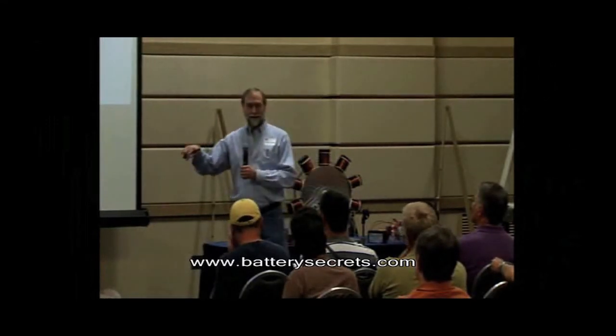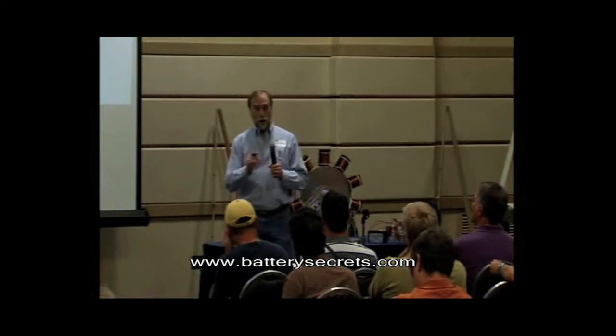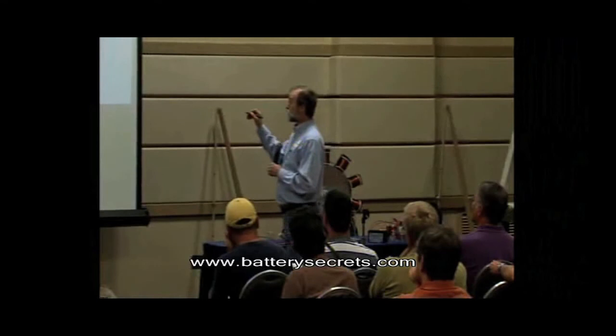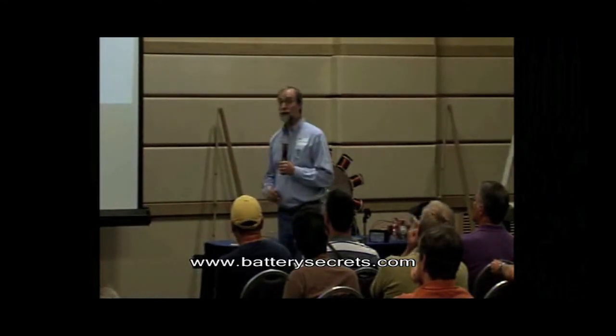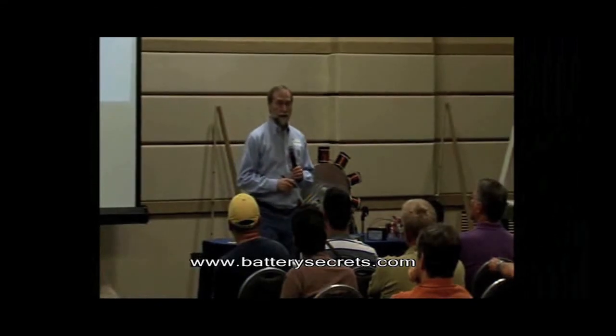And you dump all that out, and then you filter your old electrolyte and pour it back in. And quite often that will get rid of the short circuits. Yes, you can. But it's a mess.